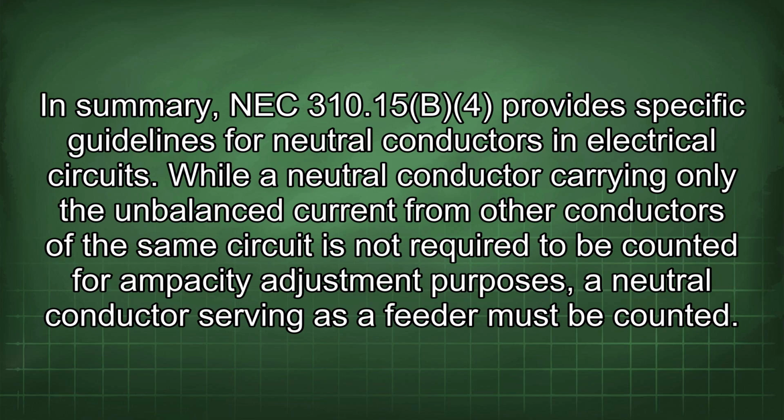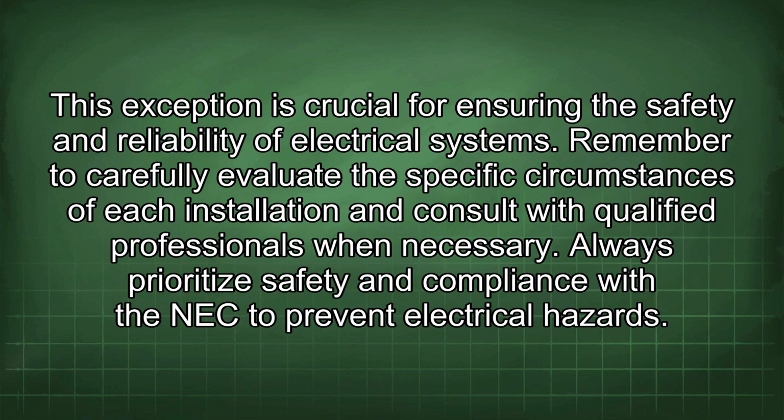While a neutral conductor carrying only the unbalanced current from other conductors of the same circuit is not required to be counted for ampacity adjustment purposes, a neutral conductor serving as a feeder must be counted. This exception is crucial for ensuring the safety and reliability of electrical systems. Remember to carefully evaluate the specific circumstances of each installation and consult with qualified professionals when necessary.